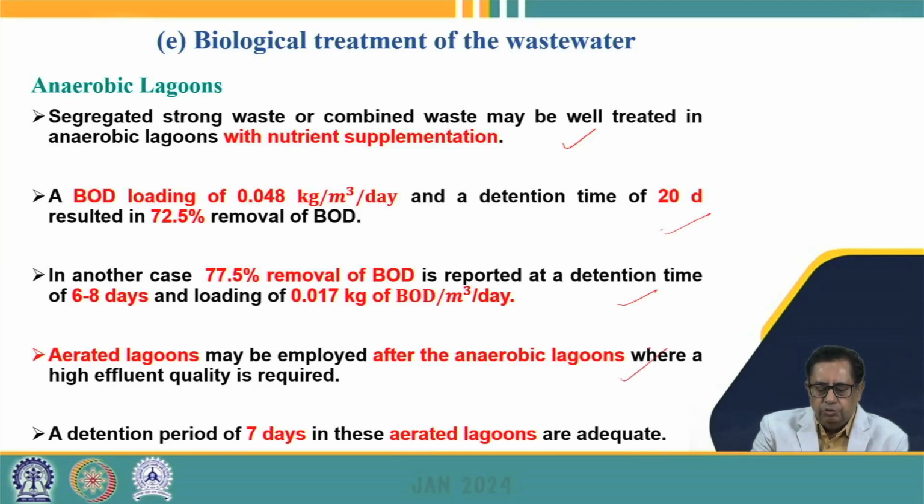After the anaerobic lagoon, it is necessary that we employ aerated lagoons also, so that the effluent quality may be enhanced and we can get a very high quality effluent, because anaerobic lagoons may result in a number of reduced products which need to be oxidized before we discharge the effluent to the receiving water bodies. It has been found that when we use aerated lagoons after the anaerobic lagoons, a detention time of 7 days is adequate.